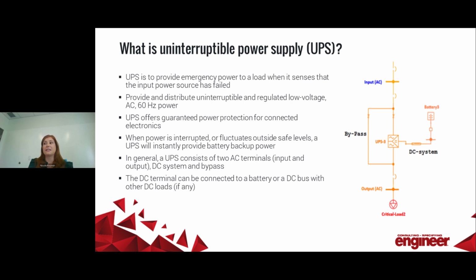So you can purchase these items separately. For example, you may want to use a facility's battery and distribution bus to supply the DC input to your new UPS. But generally, it's recommended to buy them all as a package so that the UPS's battery is specifically sized to the exact equipment it's feeding. Usually that results in a smaller footprint and a lower cost of the unit.